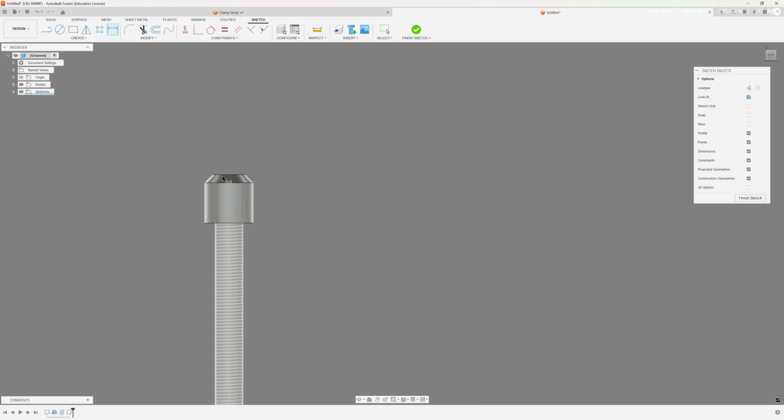Now that is beneficial because it's going to allow me to just constrain it from the tip of my pin over here, which is going to be 0.375, and let's see, from this pin over here, so I know this is 1/8, and so that is going to be 0.25, and my through hole, let's see, based on this physical print I have, is going to be 3/16, 0.187. All right, so there is my finished sketch.